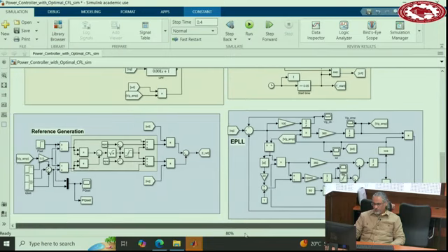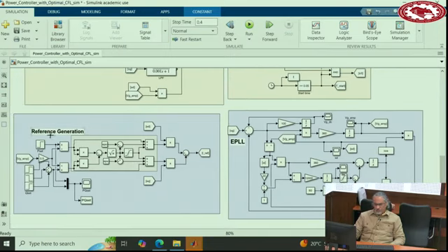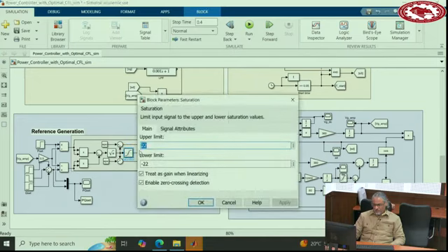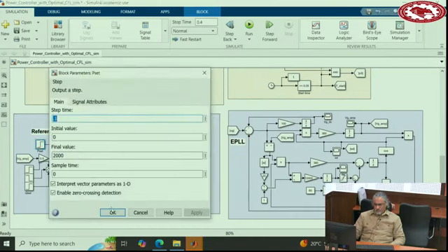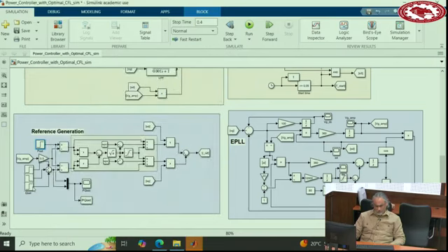Okay, there are two other things. One is the reference current generation and PLL. So this is the PLL. I'm sorry it's a little messed up, but it should be showing. This is the DC part, and this is the magnitude part, this is the phase part, and this is the frequency part. And this is the reference generation. The limiting is here. We limit at 22 and negative 22. And then you have two set points, one for real power, 0 to 2000, and one for reactive power, which we apply multiple changes for the set point. Okay.